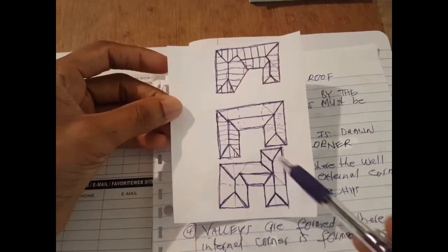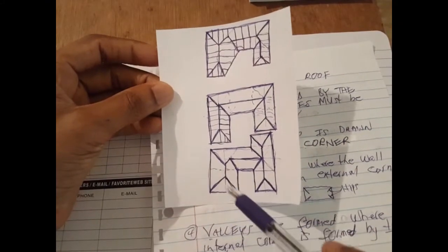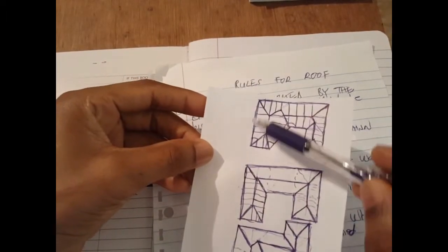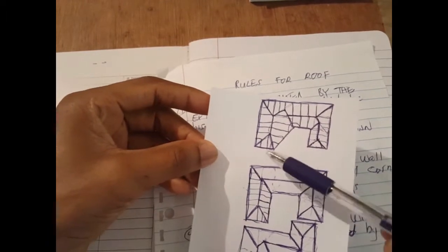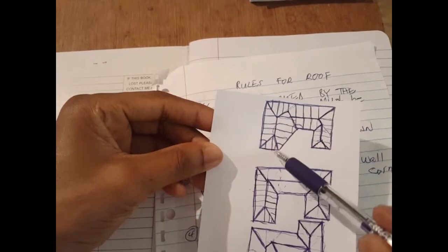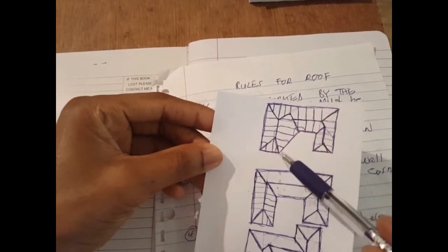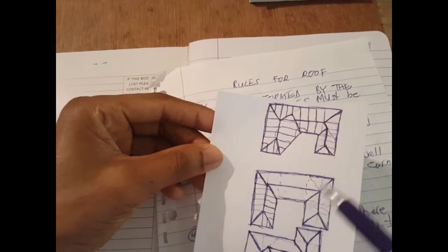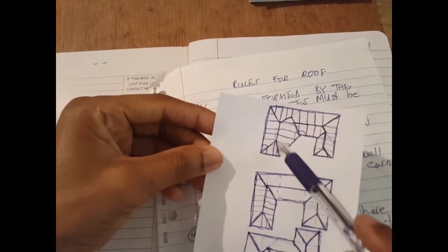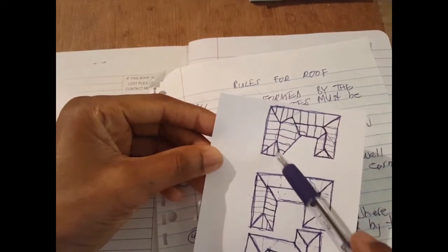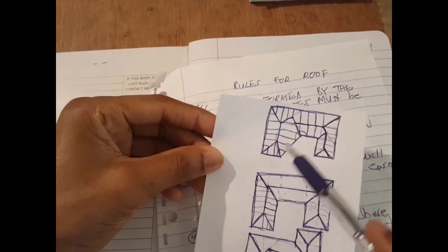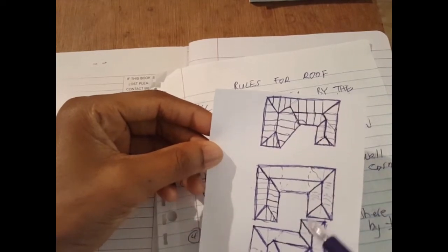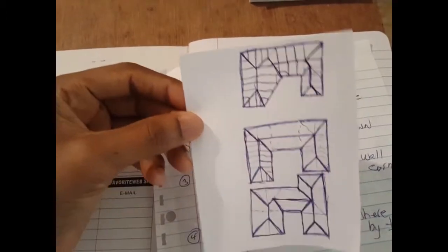Here again we have another roof outline. These are drawn at 45 degrees. All right. In cases where the roof is not rectangular, which is in most cases, we normally bisect the angle that is formed. So the rafter is drawn at the midpoint of the angle that is formed, like here at this external edge. This one is drawn at a right angle. Here, this is an internal corner. Again, we bisect this to get that at 45 degrees, half the external angle. Very important.